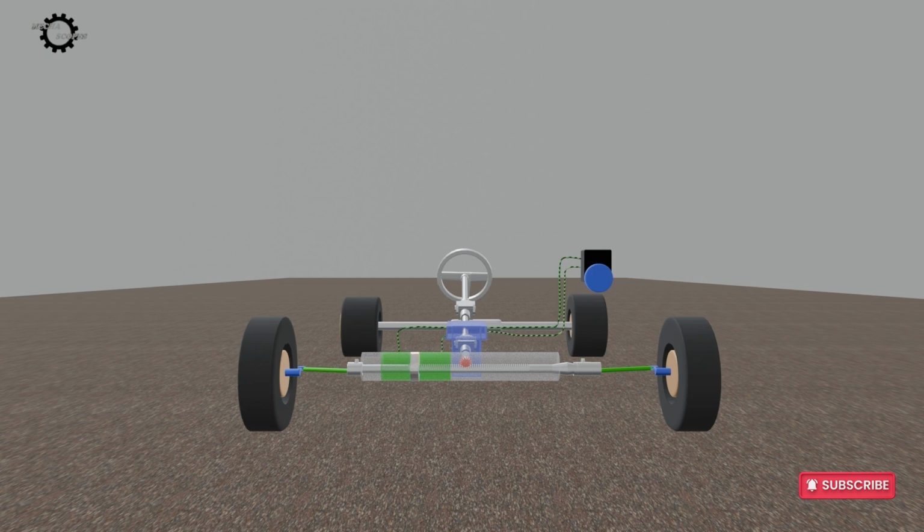When the engine is running, the hydraulic pump continuously circulates pressurized fluid throughout the steering system. While driving straight, the rotary control valve remains centered, allowing pressure to remain balanced on both sides of the piston. Since the forces are equal, the piston does not assist in moving the rack.